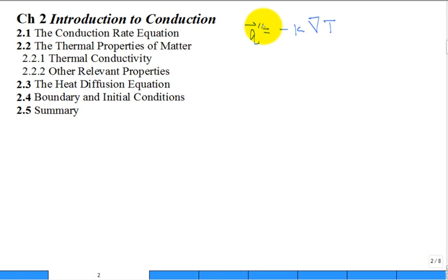All right. Now, it brings up this property known as k. What was the name of k? What are the SI units of k? What is the most common error associated with units in this class, heat transfer? People will say k has units, and this happens all the time, of watts per meter squared Kelvin.